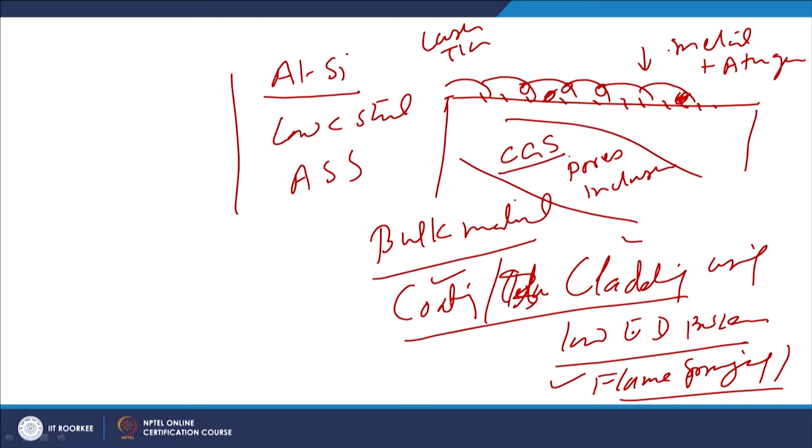Like in other cases, if the TIG remelting or the laser remelting is applied, these certainly offer a higher energy density as compared to the flame spray heat source.